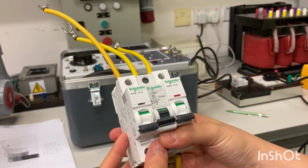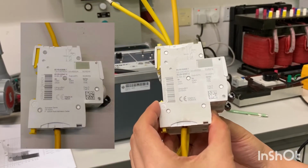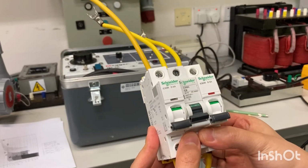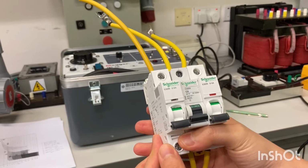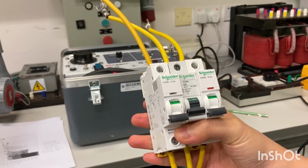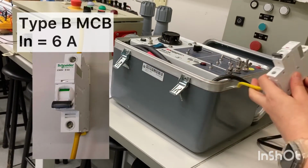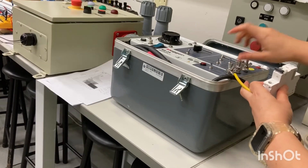So these are the three circuit breakers we are going to test. All of them have the same current rating of 6 amp, and we have type B, type C, and type D miniature circuit breaker. The first circuit breaker we are going to test is the type B rating 6 amp MCB.